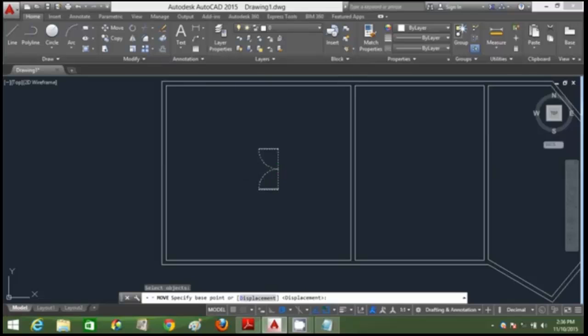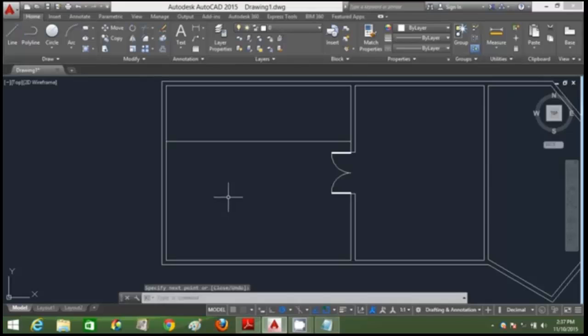Now we're going to move it to the midpoint of this wall. Wait until the object snap appears and click on it. I'm going to set the boundary of that door. Select those two lines first before trimming. Type TR and enter twice and trim out the unwanted portions. Then I'm going to mark one reference line here by 500 mm and draw this line to create the executive's office.